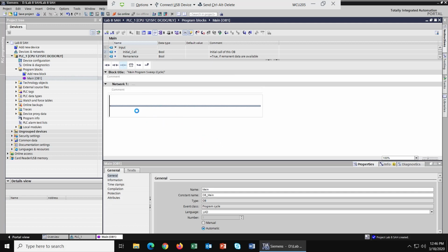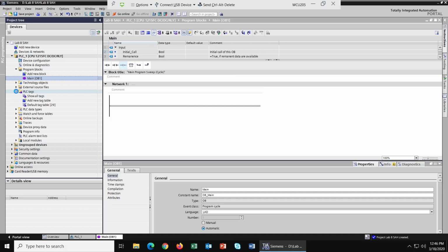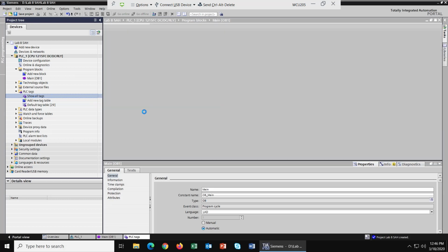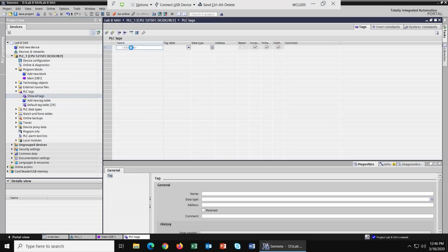I'm going to jump ahead a little bit, and I'm going to go into my PLC tags right here. And I'm going to do show all tags. Okay, let's see if that'll come up in a minute. And so I'm going to go ahead and add a new tag right here. I'm just going to call this PB1. We really don't have a PB1, but notice it's going to stick it in here at input 0.0. So that's .0, our first address.